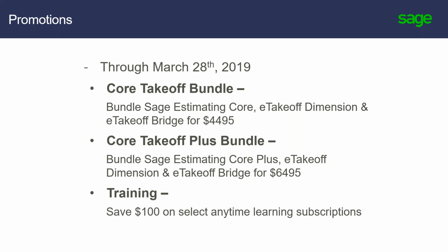For today's demo, you would need to get the Navisworks integrator from Sage, and that along with bridge would allow you to do what we did with Navisworks. If you wanted to use Assemble Systems, you would need to go to Assemble Systems to purchase their bridge, and then you would also need the Sage eTakeoff bridge. So for Navisworks, you need eTakeoff bridge and the Navisworks integrator. For Assemble Systems, you need the Assemble bridge and the eTakeoff bridge. Hope that's clear.